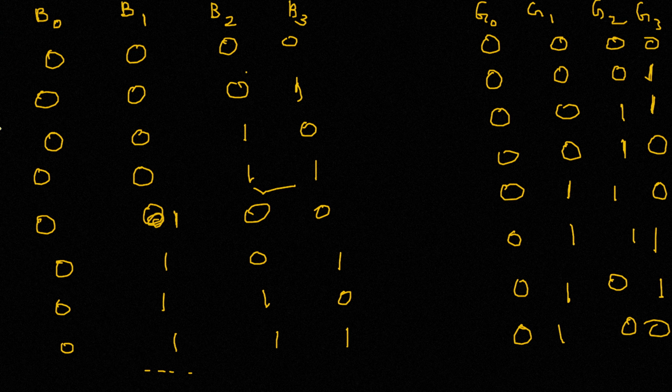I know it's an exhausting process, but the exam actually requires you to write all 16 of them and then find the value of G3, G2, G1 and G0 separately, right? So after writing all of them, you have to find the summation of minterms of each of them and then use a K-map to simplify the whole thing, right?